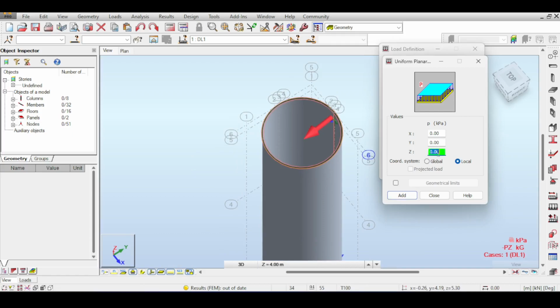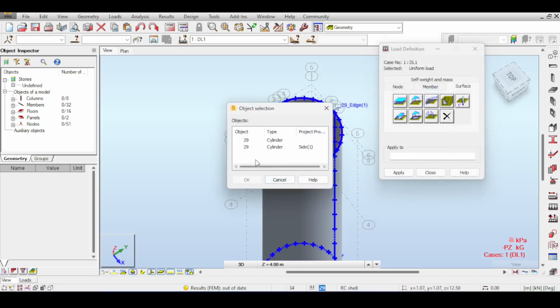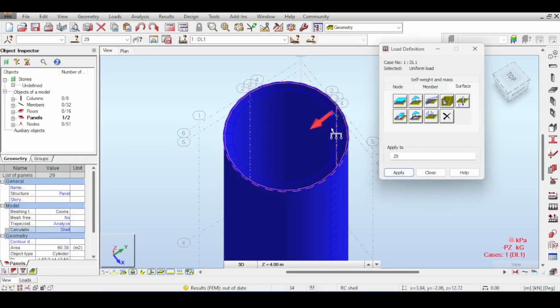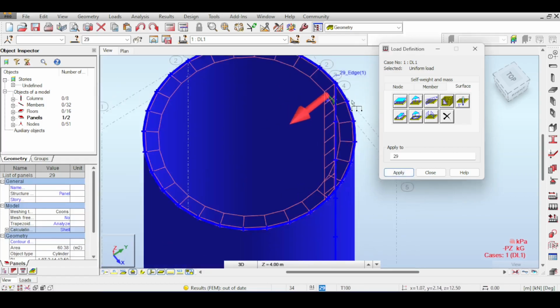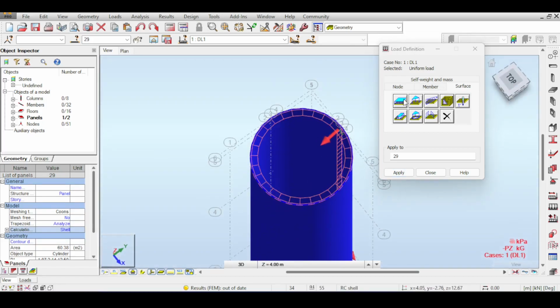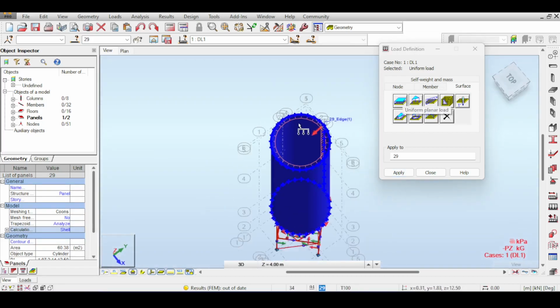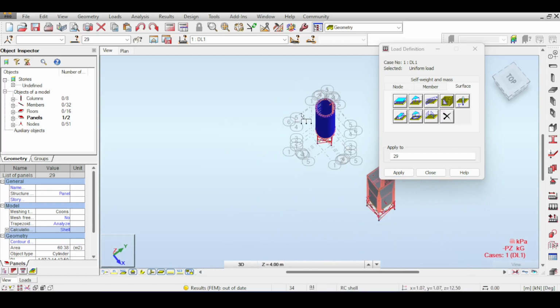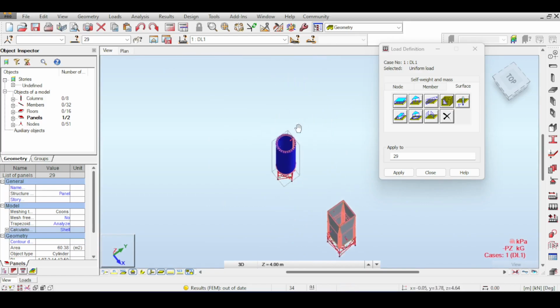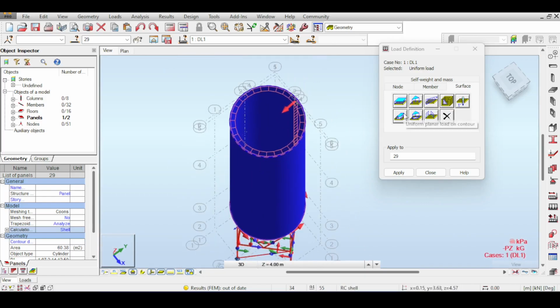So if you select, for example, local and say -10 in the Z kilopascal, just a random number here, and hit OK, or basically just select like this, apply, it works. It applies it in the local -Z10, so you have something to work with. Now the problem is that this load applies the load on the entirety of the cylinder. Now that's not the case because I want to apply it up to a certain height. So you would think contour, but remember, you cannot use contours.